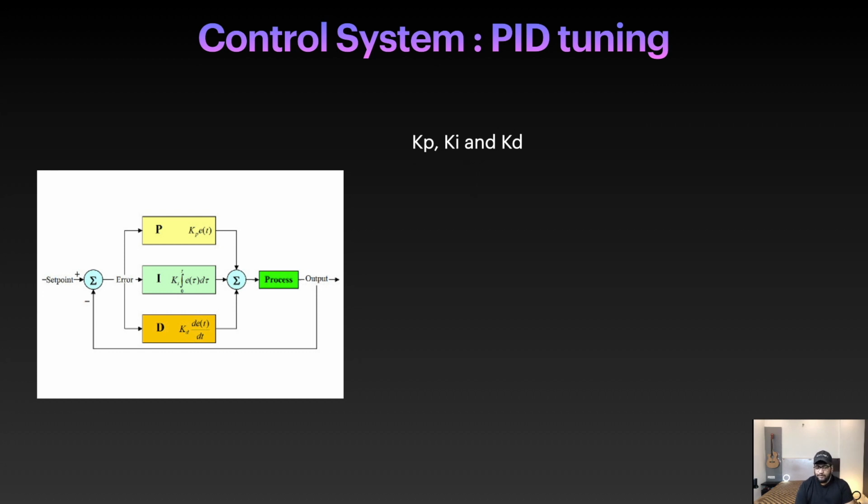So you definitely need to do PID tuning. Without PID tuning, you cannot have great results. You will be having your error multiplied with a constant which is not good for the system. Ultimately, when you build the drone and flash the firmware, the last part you need to do is to fly the drone and see if these values are good. If not, then you need to change them.